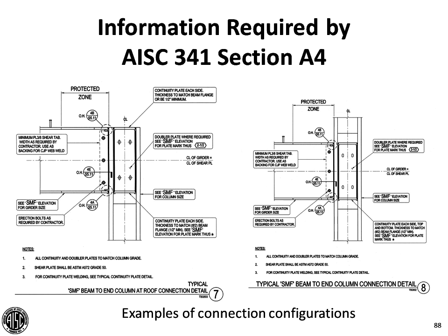Here's similar conditions, except looking at it at the exterior of the frame, both at an interior or an intermediate level as well as at the top. And so in laying out these things, you need to give some thought as to the different conditions that need to be reflected in the details, and that showing just one moment frame detail sometimes might work, but it usually makes it easier and invites less confusion if the engineer has taken the time to show these things. And since these are generally typical details, the time spent in developing them can be leveraged on other projects.